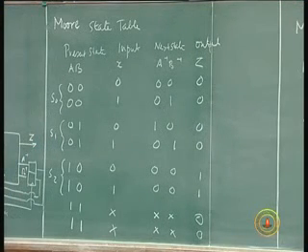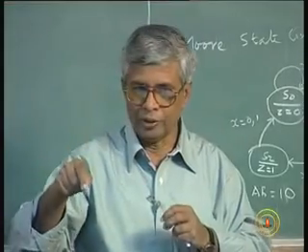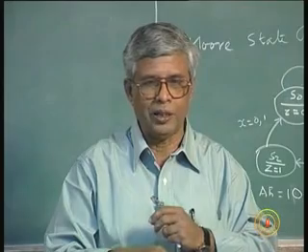We will start with a simple example of a state graph. So you also should know how to draw one, because so far I have been assuming state graphs. I never told you how to draw the state graph. Of course, in the case of counters, if I give you the count sequence, you know how to draw the state graph, because each count is a state. So put one circle and then put the count value inside and then go to the next count, put an arrow. That is one way of doing it, but that is a very simple way.